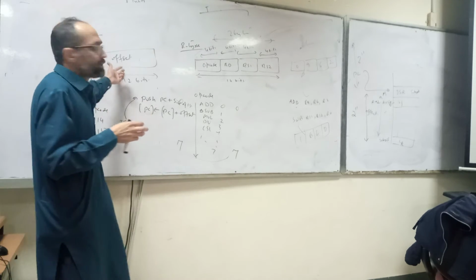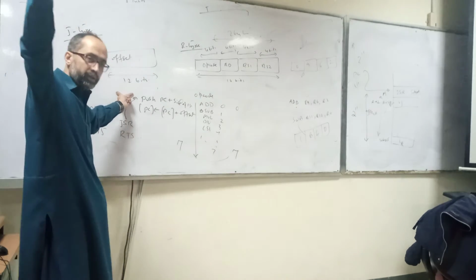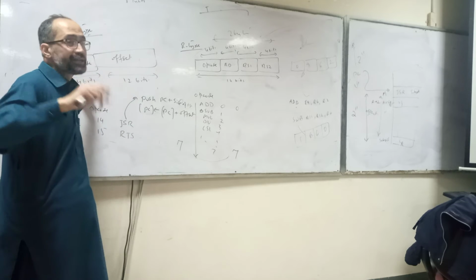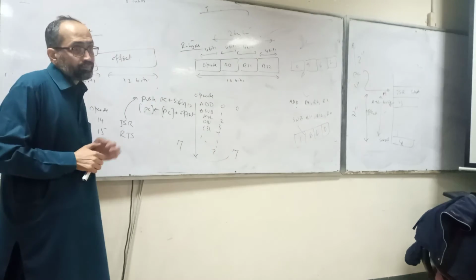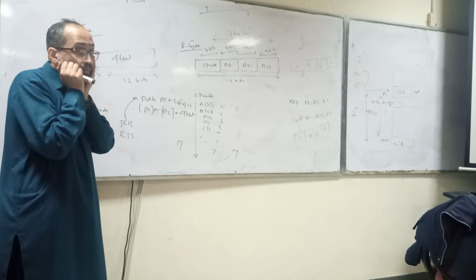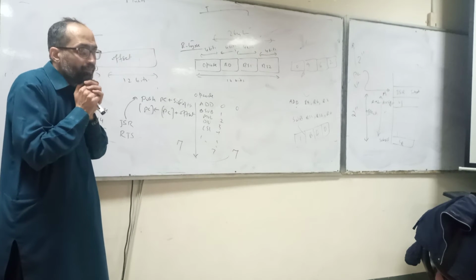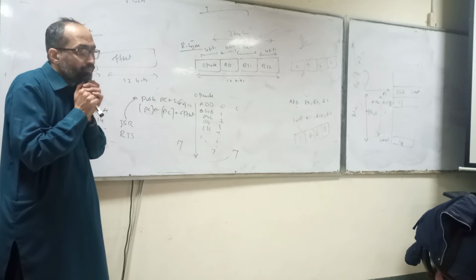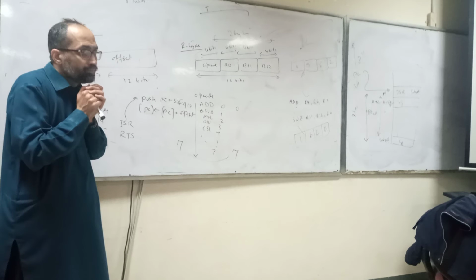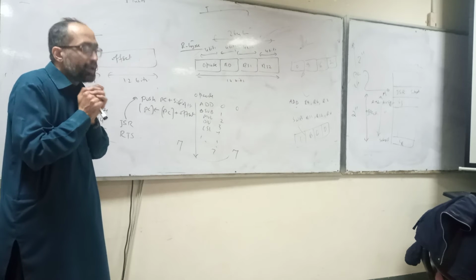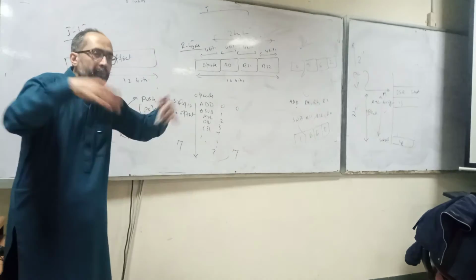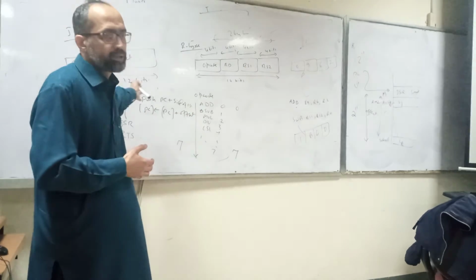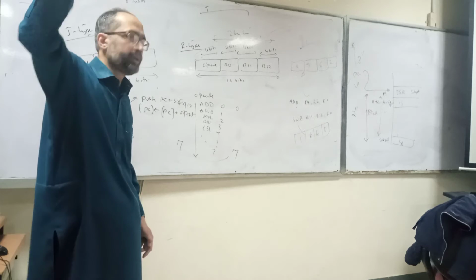Actually the size of the offset is not 12 bits. Typically it's more than 20 bits, more than 30 bits. Similarly the opcode size is not 4 bits. This is just for elaboration, to have some correlation within the particular example about the budgeting of the number of bits, like the total number of instructions being only 16. If you look at a complex or simple microprocessor, it does not support just 16 instructions. It supports 200 or 300 instructions.